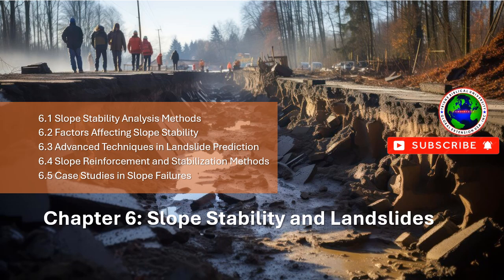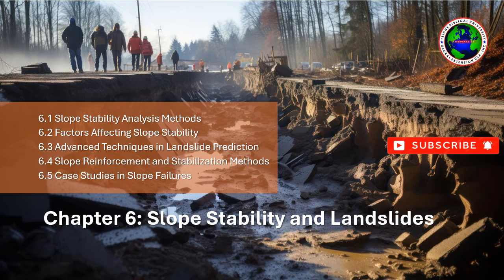Continuous approach. Unlike LEM, which focuses on force equilibrium, FEM solves the equations of motion for the entire slope, accounting for deformations, stresses, and strains within the material. Soil heterogeneity.